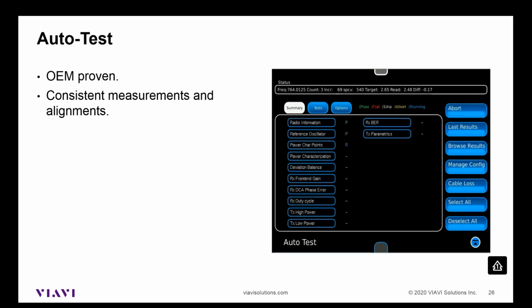And what you end up with is this hodgepodge of different alignments of radios out in the field. And remember, I mentioned earlier that the frequency and deviation are critical to that digital radio's performance. Well, if you have a bunch of different radios out in the field that are all aligned with a little bit different deviation, you're not getting the best range out of those. And so in those situations where someone's out at the corner of the county or is in the basement of that hospital, they may not be able to get a signal where they should be able to.